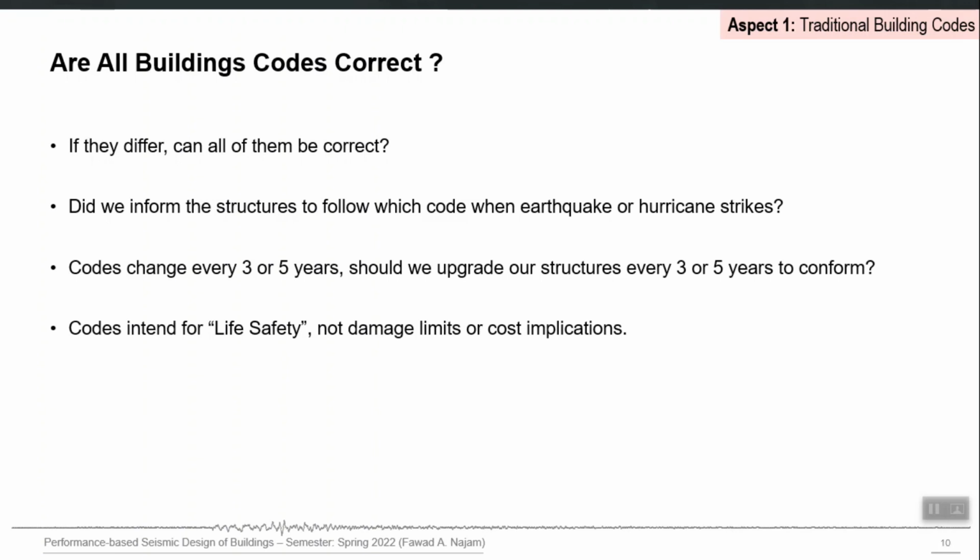So building codes allow the use of performance based philosophy for your buildings if you can justify it in front of an authority which regulates the building structural design at your site, right? So that impression that PBD is somehow against or violating the building codes is not correct. All building codes allow the use of alternate procedures if they can be justified, right? Which means that we must have a parallel legal framework associated with PBD which regulates the PBD process, and if that system gives legal authority at a particular site to PBD, then PBD will become an authorized legal design procedure in parallel to the code, right?